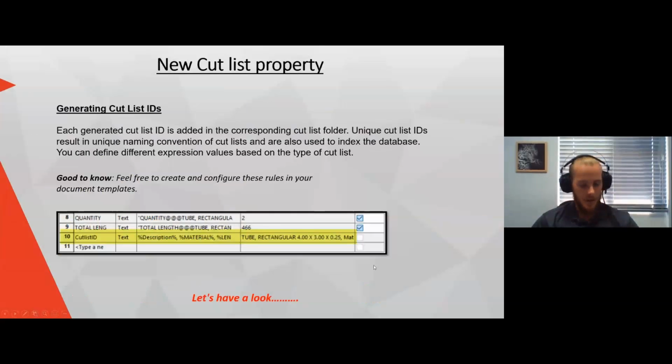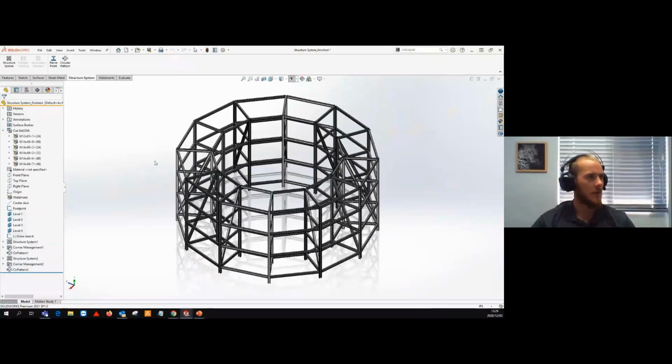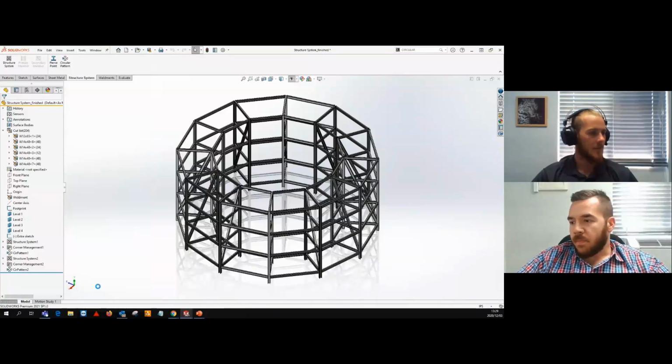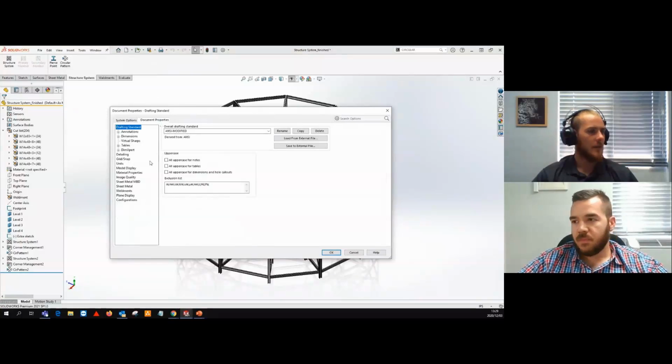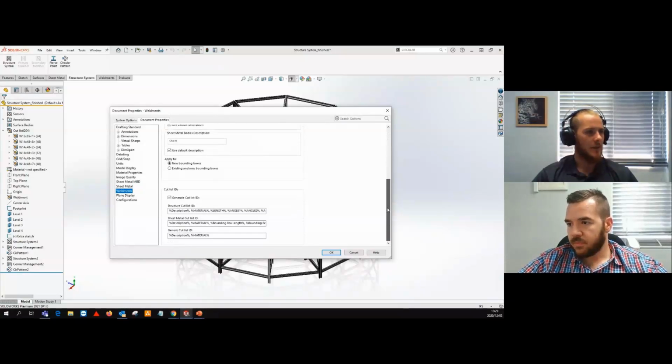I'm going to quickly jump into SOLIDWORKS and show you guys where to find that setting or tool. Then I'm going to ask Pierre to jump in and join us in this webinar to showcase what this means inside of a PDM system, specifically looking at the BOM within PDM. So what you're going to need to do is either click on this options over here or navigate to your Tools drop-down, and you'll find it all the way down there. Once accessed, go to Document Properties, navigate to Weldments, and if you go all the way down, you'll see there's the little checkbox.